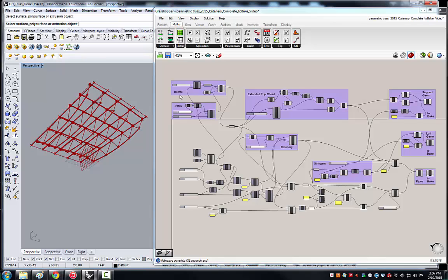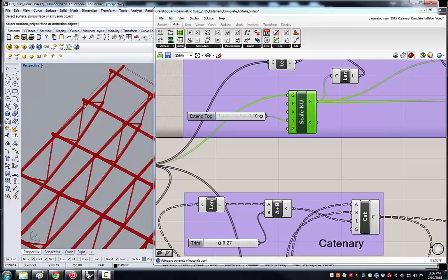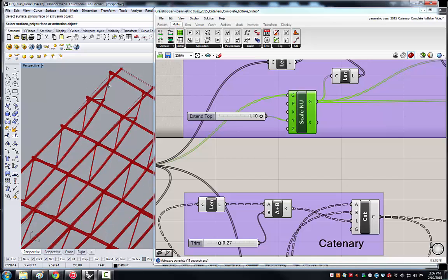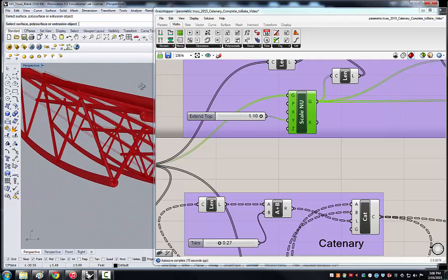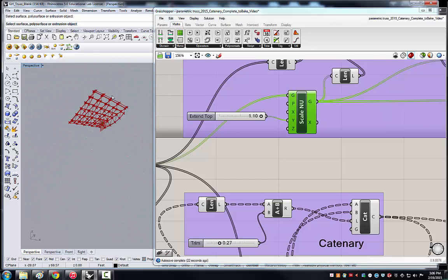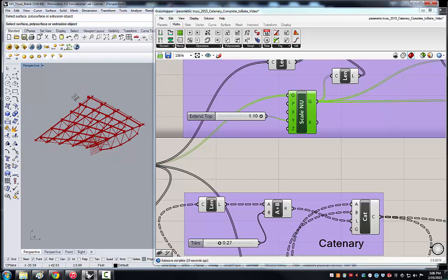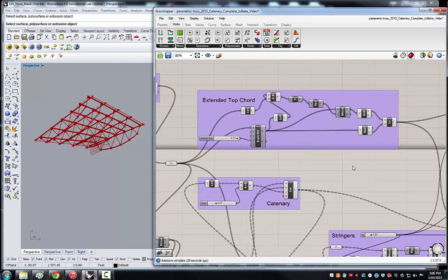As soon as you start to rotate these, the extended top chord using the scale function along the x actually causes this new top chord, the extended one, to diverge from the geometry of the intended top chord. And I think you can see that when you look at each end of this in an extreme case. When we were only having a few of these and having them rotate very little, or if there were no rotation, this scale component works fine for extending the top chord.